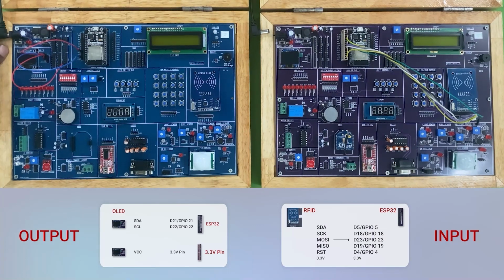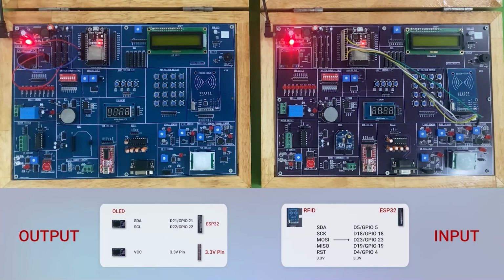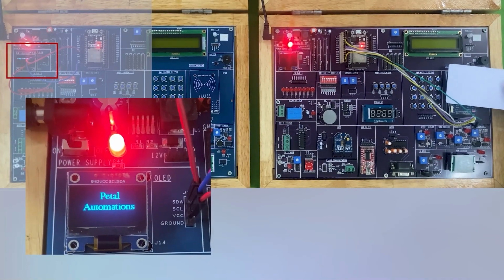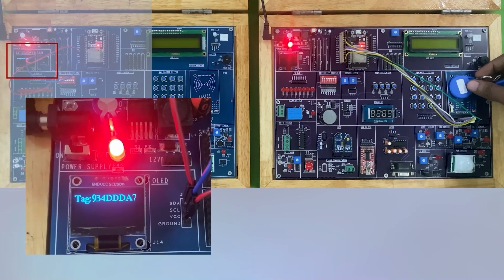Power both the IoT kit by connecting the adapter. Now refer the Wi-Fi video to connect the ESP32 with Wi-Fi. Now tap the card or device in the RFID and see the tag ID in the OLED display in another kit.